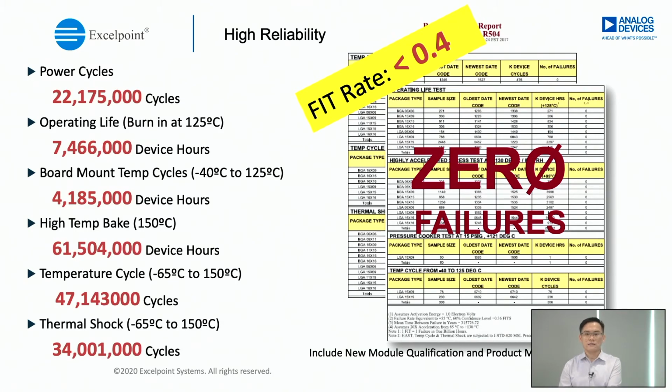And all of these µModules come with very high reliability. You can see from here some of the testing conditions that the µModule have been put through to confirm the high reliability, for example power cycle, operating life, mounting temperature, temperature cycling, and thermal shock. The ultimate target is zero failures, and so far the FIT rate is below 0.4, which is very, very impressive.